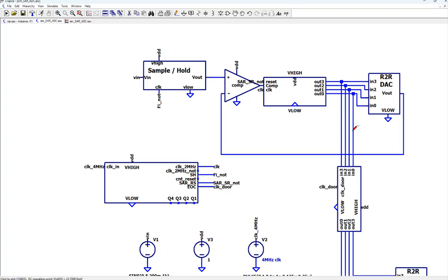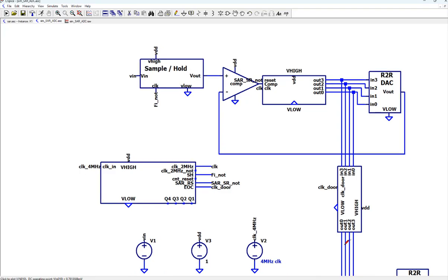You should send a rising edge to the DAC. So we got the first data over here. Then what? You don't have to close the door. It's a rising edge trigger. There's no way to close it. You open it once, that's it. It's a rising edge, it's done. Nothing can go through. It's waiting for another rising edge.